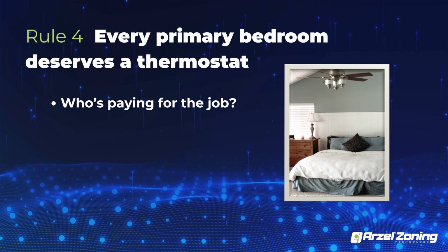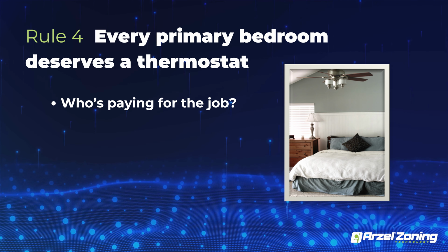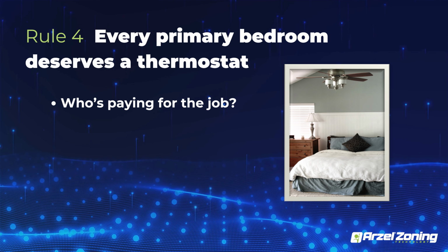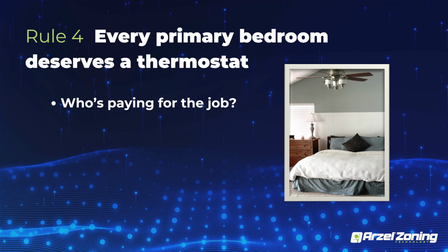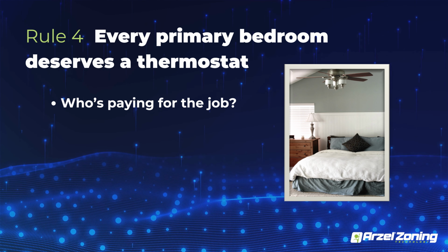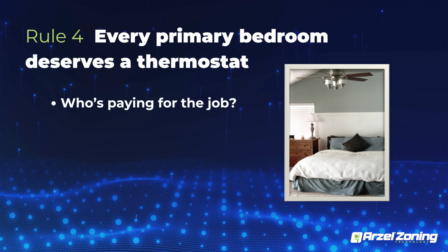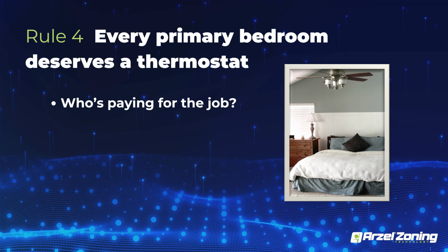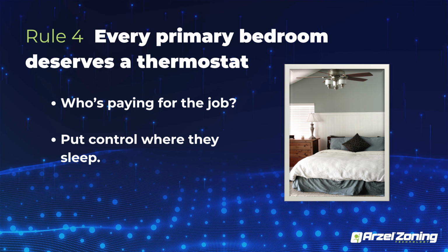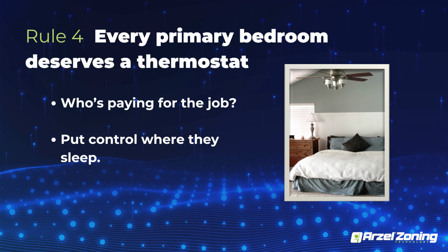Not as happy, right? So either make sure it's sensing and averaging rooms, or make sure that if the second floor is only getting 1 thermostat, you put it in that bedroom. That bedroom deserves to be spot on every night when they go to bed. You're basically putting the control where they sleep, and those are the happiest customers.